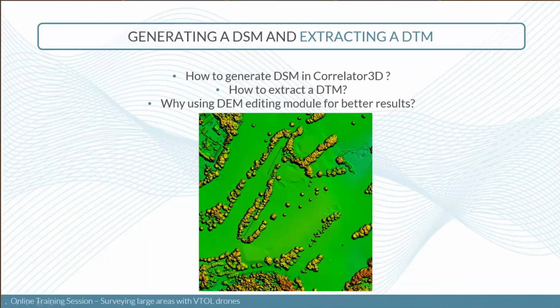One thing that you really need to be aware of is that the resolution of your DSM will have a big impact on your processing time. So you really need to ask yourself before starting your project, what is the resolution I need for my project? Do I really need something at a high resolution? Or should I go maybe with a lower resolution depending on my needs? Do I need to generate a point cloud? Basically, you just ask yourself all these questions because it can make a very big difference in the processing time.